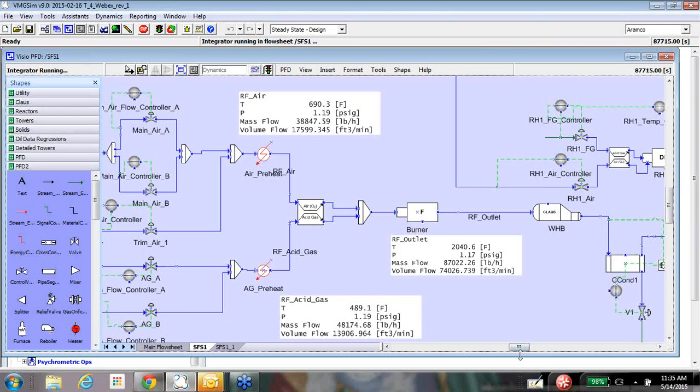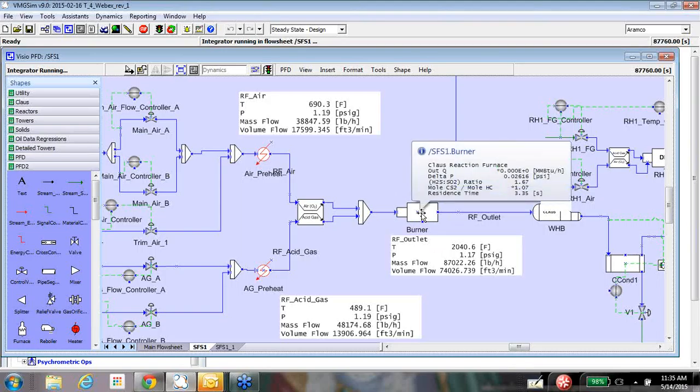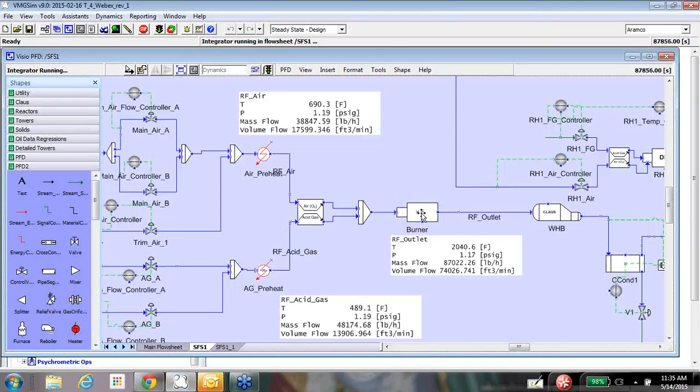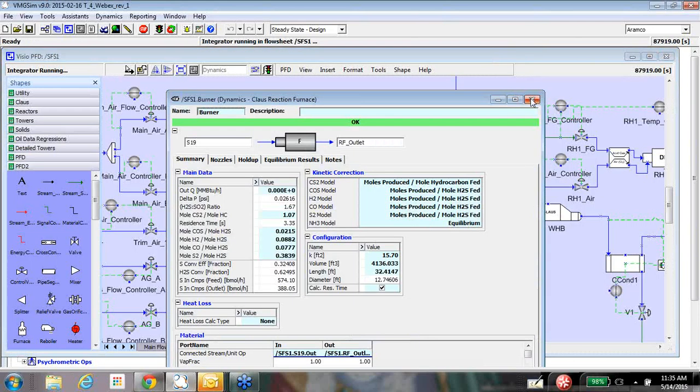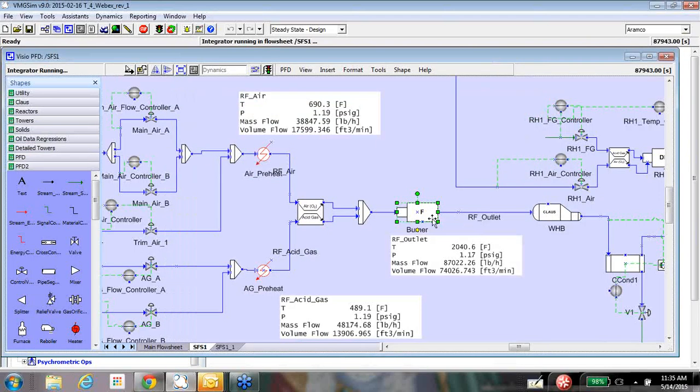Okay. So, for example, as I mentioned before, while we run the plant at a particular steady state or normal operations, at the same time we also take a pressure profiling. The real reason for taking that is that using that information and DCS data as another parameter, we set up the pressure drop tuning parameter for each equipment, which represents, for a particular flow rate, what would be the pressure drop across the equipment.